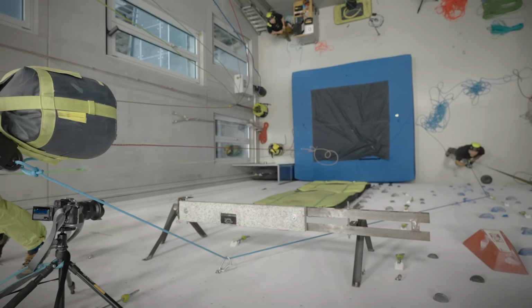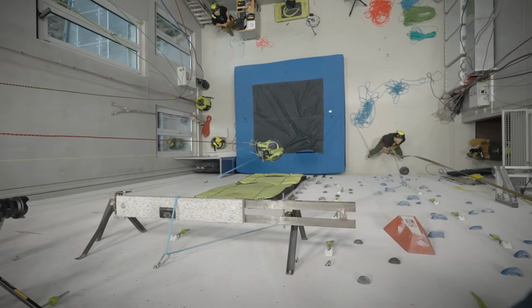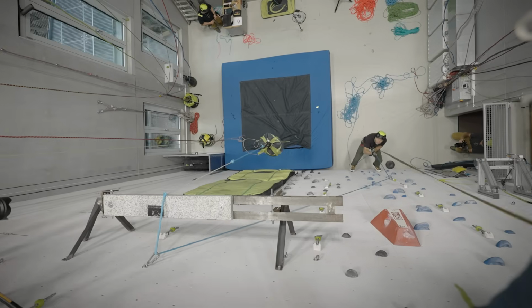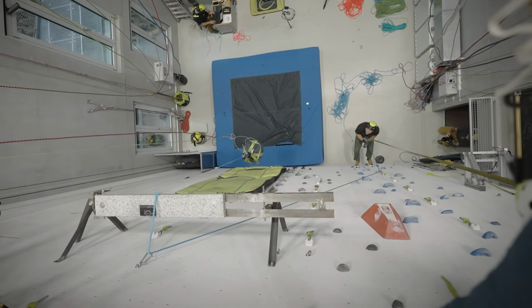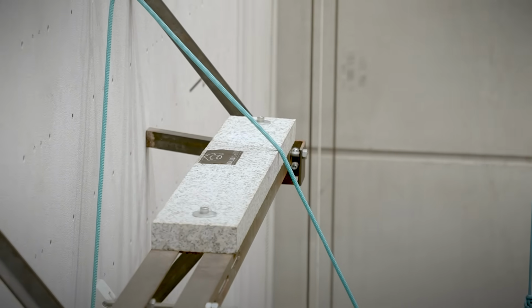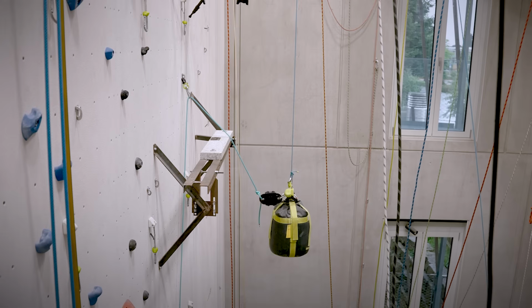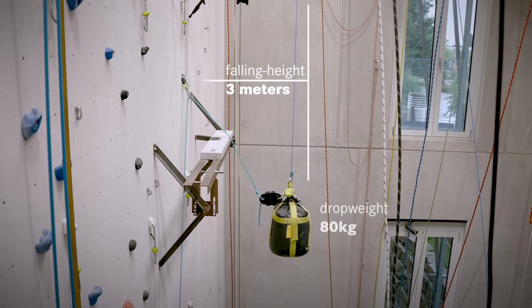It's been pretty cool. The plan now was to choose a testing setup in which the weakest rope of them, according to our lab test, would just fail, and then see if the supposedly stronger ropes on the cutting machine endure these same testing parameters. And that would provide us some evidence if the tendency the lab test suggests also holds up in the real world. And that made us finally end up with an 80 kilogram drop weight lifted 1.5 meters above the redirect, so effectively creating a falling height of 3 meters.